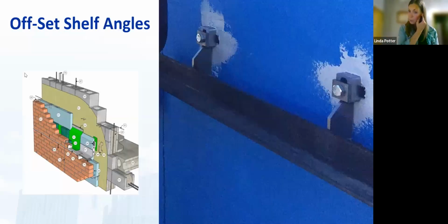That's why you've seen a big push, when shelf angles are part of a project, toward an offset shelf angle system, which allows you to have something to air barrier entirely before you attach the shelf angles, and then you're just detailing around those areas. It makes it faster, and it is extremely important to the overall impact on your air barrier, whether you can get that fully continuous or not.